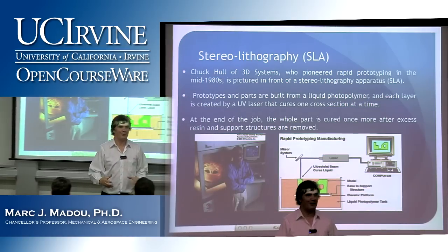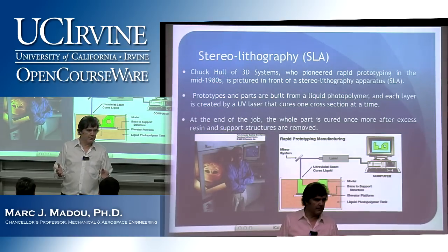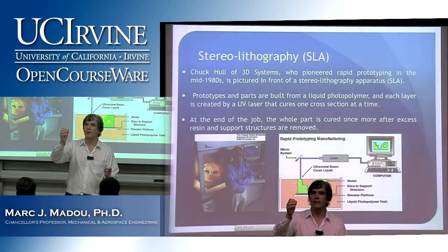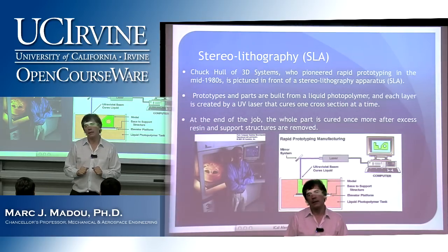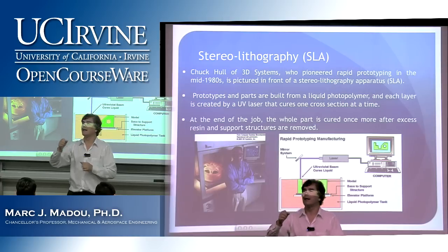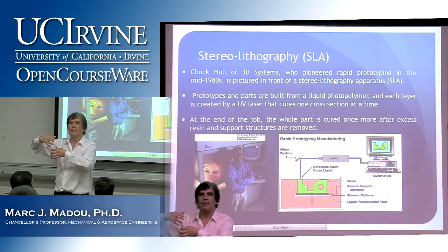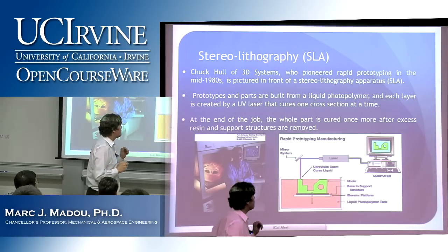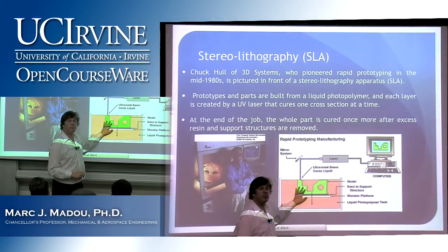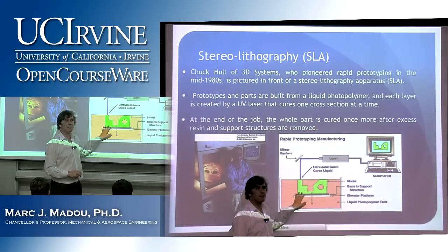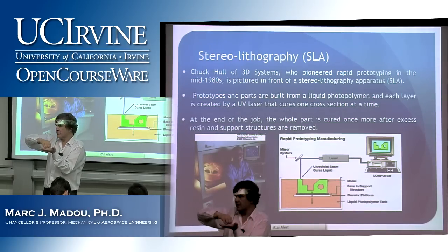I love this idea. You have to just think about it. It always has something in common. What do we have always in common? The stage, right? X, Y, and Z. It has this too. In this case, I'm not putting molten lines of plastic on it or a powder. In this case, I submerge my stage right here in a photopolymer solution. And that solution, when the laser hits it, gets solidified.